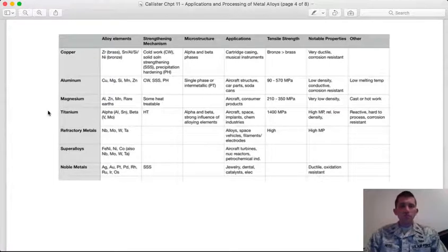I can think of these as sort of aerospace alloys because of their high specific strength, right? They're low density. And then you've got a little more exotic, where you have your refractory metals here, distinguished by really high melting points. Your superalloys. Oh, and I guess maybe, yeah, sorry, earlier I misspoke. Your precious metals aren't buried under copper. They have their own category here, the noble metals.